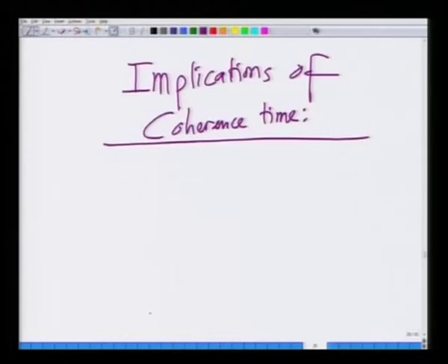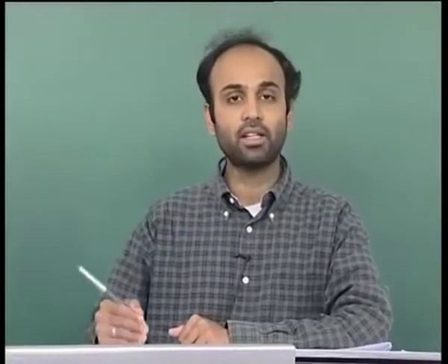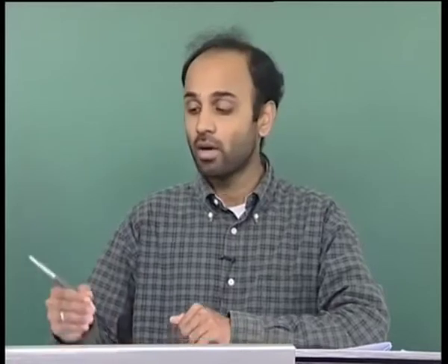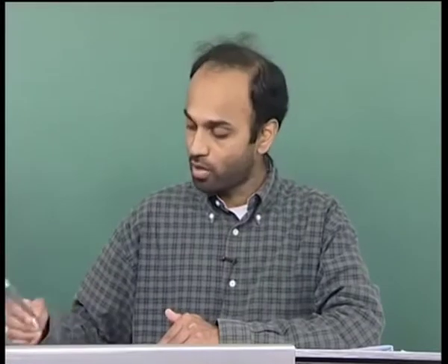Remember, the channel is changing; it's constant for the coherence time, and it changes from coherence time to coherence time. Hence, if you want to know about the channel, you need to measure it at least once every coherence time. Hence, to get knowledge of the channel, it needs to be measured at least once every coherence time.